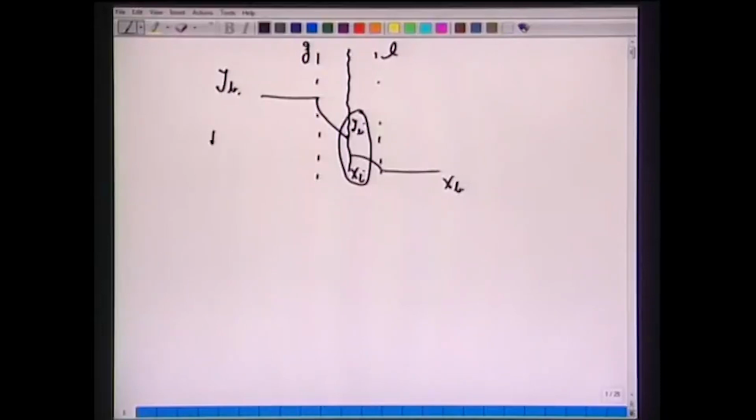In the gas phase we have some Reynolds number. In the liquid phase we have some Reynolds number based on the flow rates. So this Reynolds number decides what is the individual mass transfer coefficient in the gas phase and in the liquid phase, based on Reg and Rel.